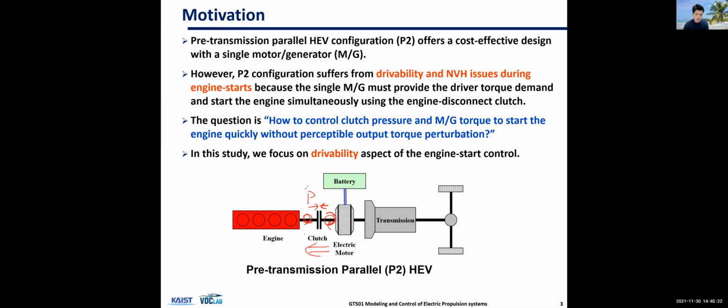And now engine will provide power to the drive line, right? And then now you have more power from the engine and motor. But until that point, until engine can provide power using fuel and firing, you need to consume energy.